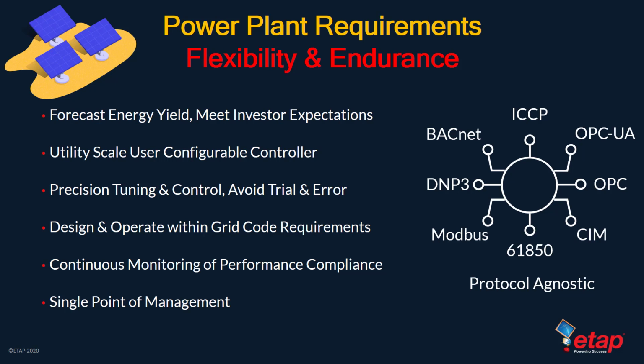Finally, a single point of management is needed for remote monitoring of plant performance. A monitoring system is an essential part of a PV plant. Monitoring devices are crucial for the calculation of financial damages and confirmation that the EPC contractor has fulfilled its obligations. Automatic data acquisition and monitoring technology is also essential during the operational phase in order to maintain a high level of performance, reducing downtime, and ensuring rapid fault detection.